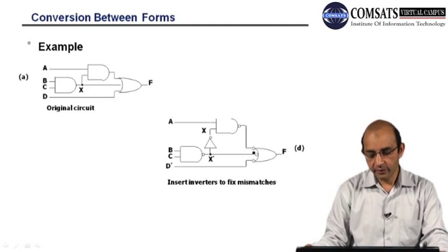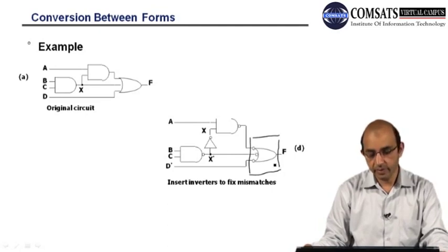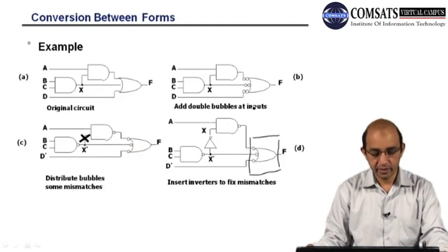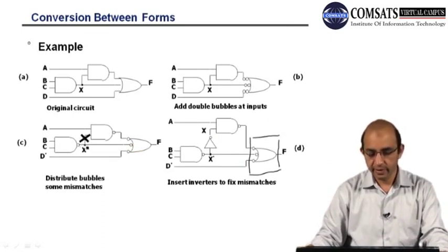And then we will be placing a NAND gate, an OR gate with complemented inputs can be replaced by a NAND, right? So there is a difference here. That's what I have mentioned, that we have to handle this externally.